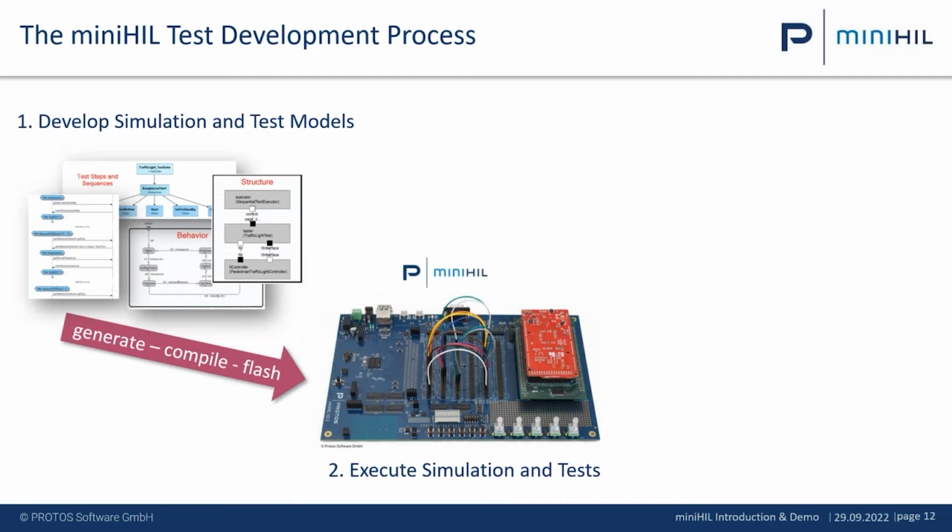In order to have hard real-time execution, we can go down into the range of, let's say, 10 microseconds with a test case. Typical motor control simulation runs with 15, 20, 30 kilohertz. So it's really important to have a hard real-time system as a test system here for this kind of test.